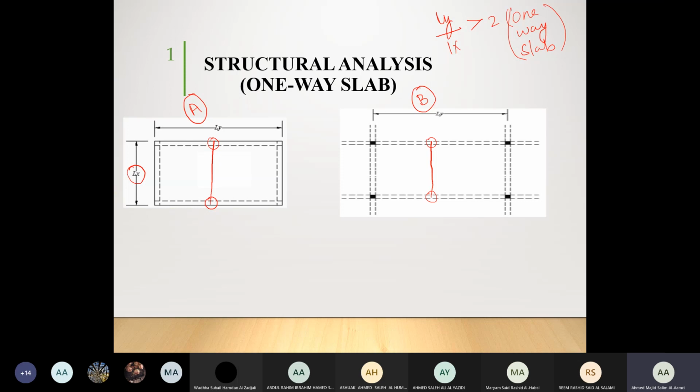You have studied that we have a hinge, a roller, and a fixed support, right? Once again, hinge, roller, and fixed support. Now, when it comes to RC design, or real designing, especially in RCC, we shouldn't call them hinge, roller, and fixed. Rather than calling them these, we are going to call them continuous and non-continuous.